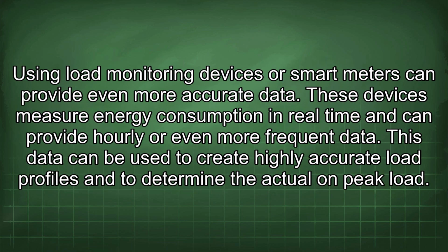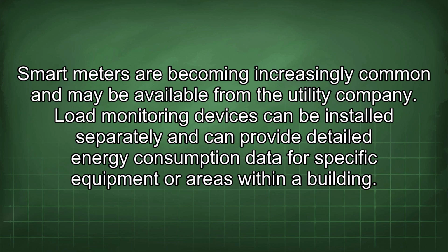Using load monitoring devices or smart meters can provide even more accurate data. These devices measure energy consumption in real time and can provide hourly or even more frequent data. This data can be used to create highly accurate load profiles and to determine the actual on-peak load. Smart meters are becoming increasingly common and may be available from the utility company. Load monitoring devices can be installed separately and can provide detailed energy consumption data for specific equipment or areas within a building.